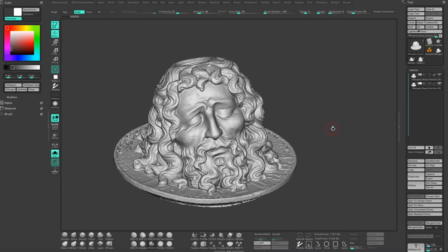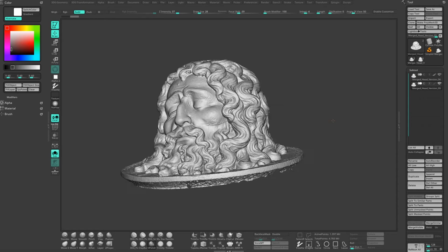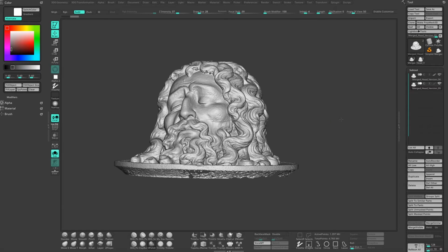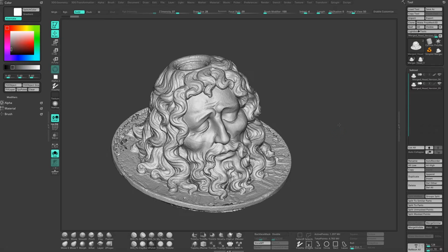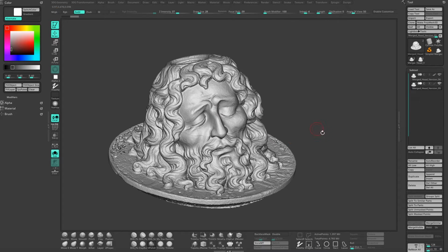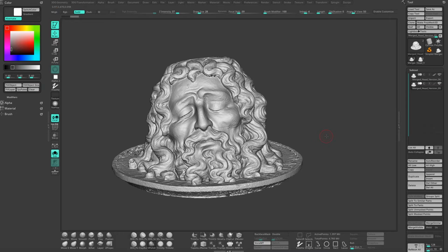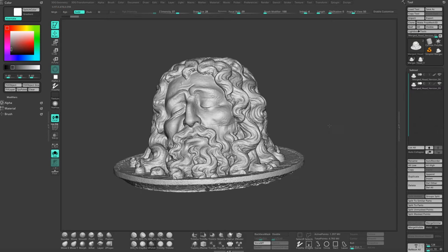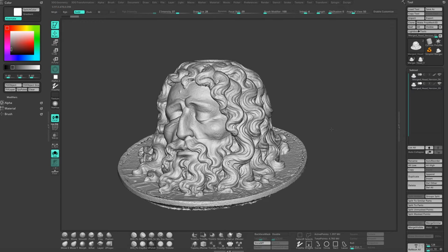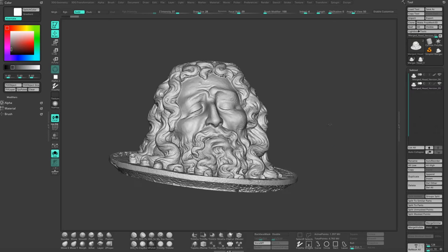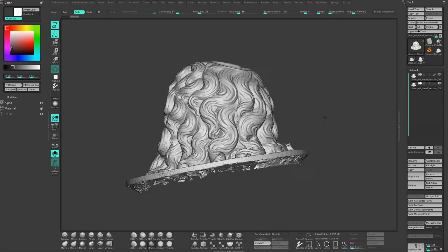So you basically take a lot of pictures from different angles of one object, and then you import all of these images into a special software where the pictures get aligned, and by aligning these pictures the program is able to calculate a point cloud, and then you can turn the point cloud into a 3D mesh and export the model also with textures as a 3D model in a common file format. And that's the exact way how this one is created here.